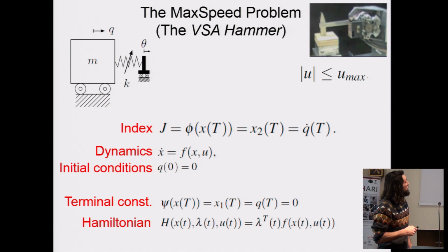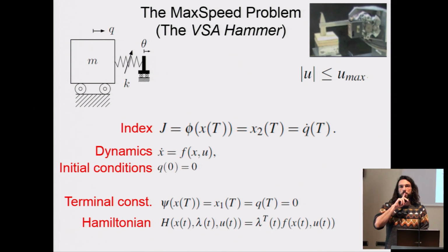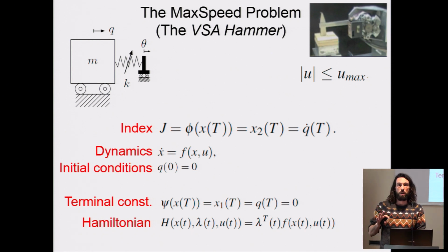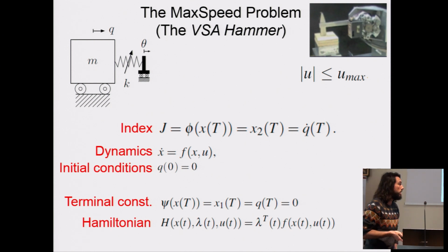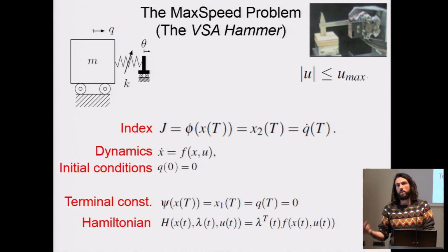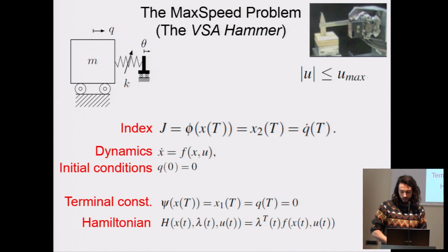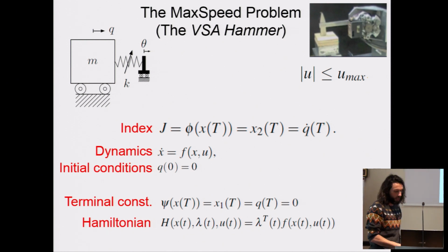First, we studied the problem for the series elastic actuation. Why? To see if there is an optimal constant stiffness value for maximizing the peak speed of the actuator. And then we switch to the variable stiffness case in order to see if there are any advantages in changing the stiffness during the task, and above all, how the stiffness has to be changed. So now let's see the results for the series elastic case.